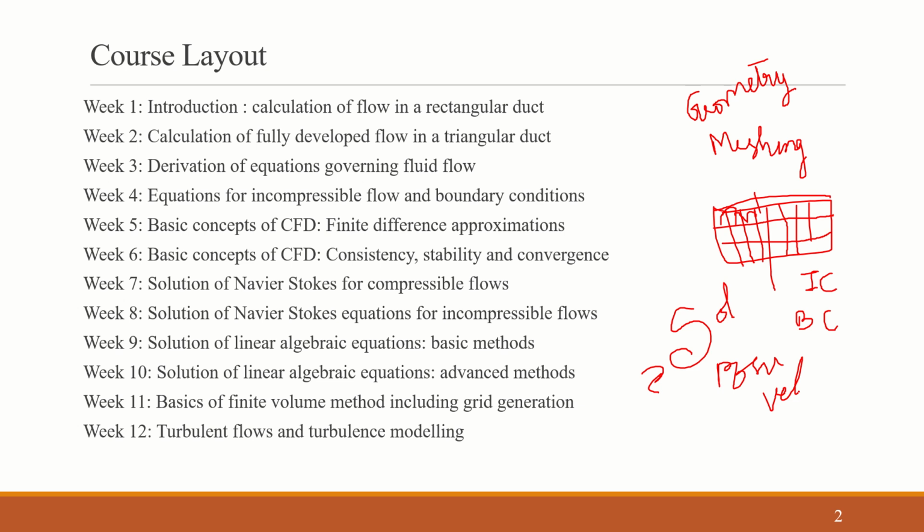For us to get meaningful results, we need to define everything rightly, and the solvers should also be appropriately chosen. It is in our hands and we should choose wisely, because at last we will be post processing the results and getting colorful images, like velocity contours. If we are saying velocity is high at one point, low at another point, those contours we will be using to visualize the results and present this data. So if we are not focusing on utilizing the correct approach, we will be left with colorful diagrams, but not the correct ones.